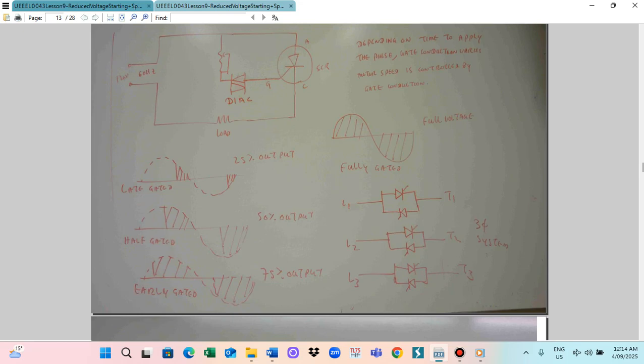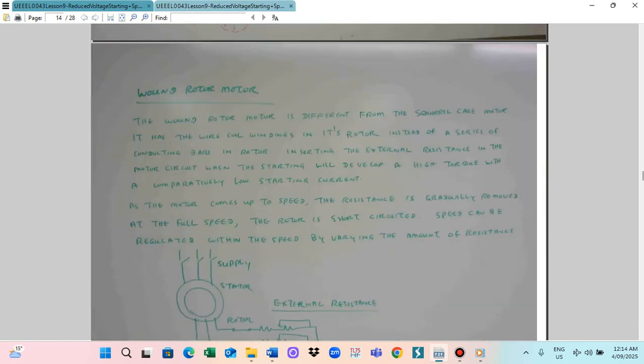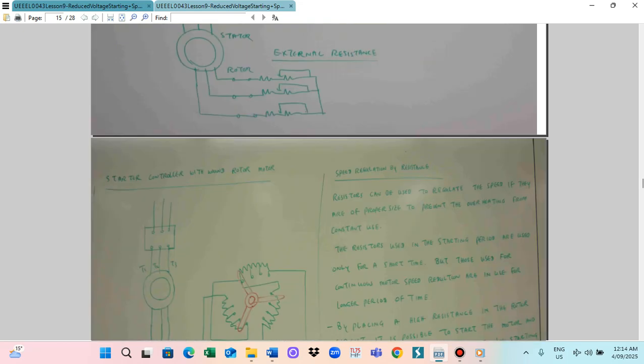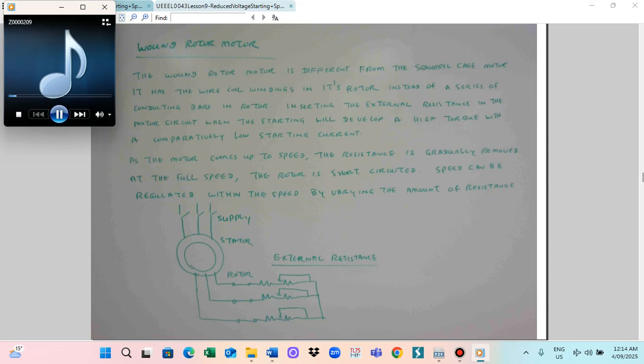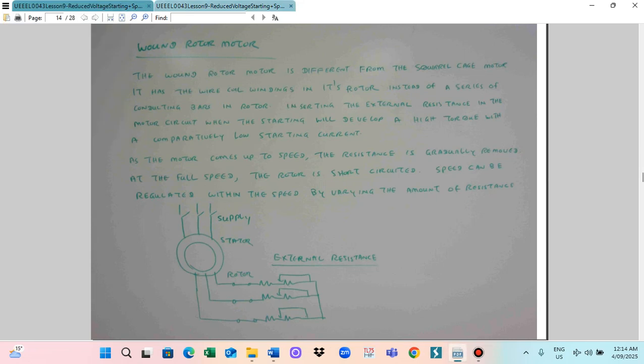If we draw a higher current, a starter must be used for the speed control machine. When you start the induction machine, the induction motor usually draws a higher current from the supply. So this current needs to be reduced. This is where we have to utilize the reduced voltage starter.